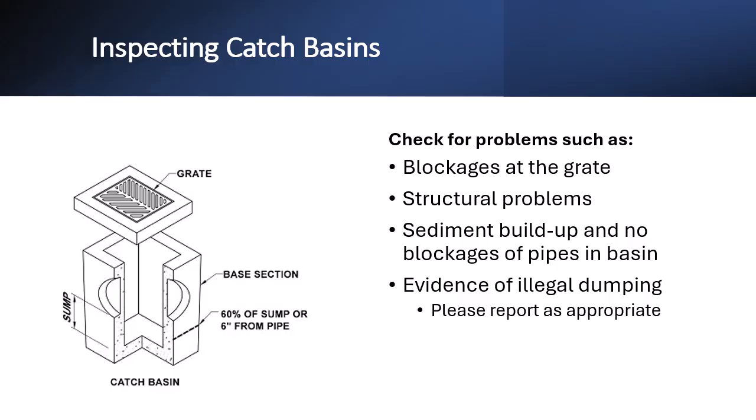Like other inlets, when inspecting a catch basin, check for problems that can impede the catch basin's conveyance of stormwater flow. There should be no blockages at the grate from sediment, litter, leaves, pine needles, plant growth, or other debris. In winter, snow and ice may also be problematic.